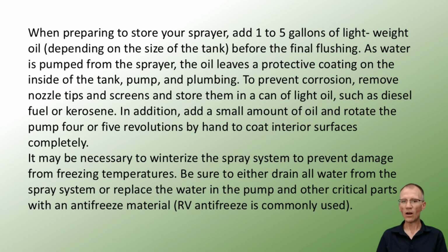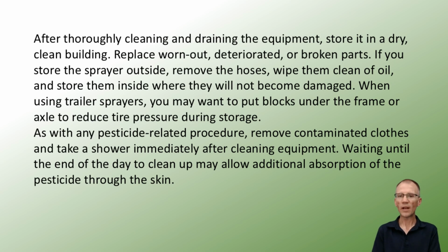Be sure to either drain all water from the spray system or replace the water in the pump and other critical parts with an antifreeze material. RV antifreeze is commonly used. After thoroughly cleaning and draining the equipment, store it in a dry, clean building. Replace worn out, deteriorated, or broken parts. If you store the sprayer outside, remove the hoses, wipe them clean of oil, and store them inside where they will not become damaged. When using trailer sprayers, you may want to put blocks under the frame or axle to reduce tire pressure during storage.